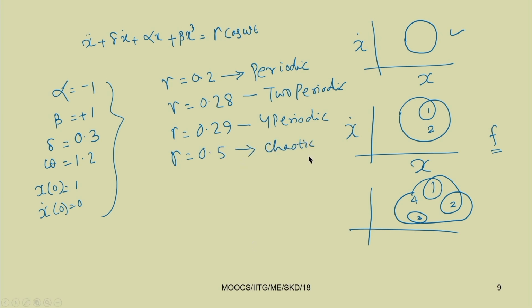Chaotic means it contains many harmonic terms, more than 16, or around 30 harmonic terms. So, the response is chaotic. Chaotic responses are deterministic, but they contain many harmonics, and you cannot distinguish them from the time response and from the phase portrait. So, we can easily check that the response is chaotic.